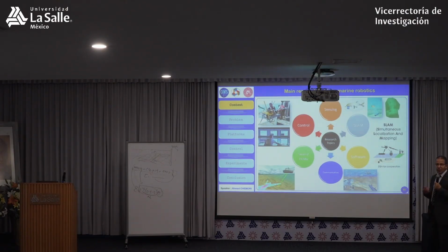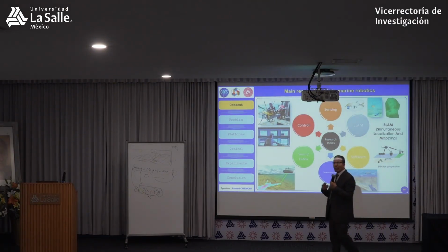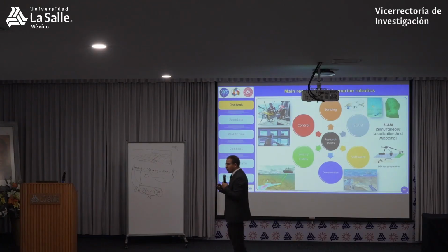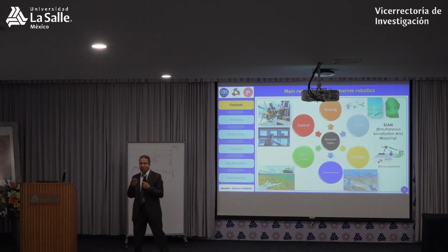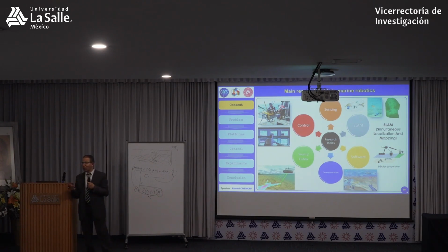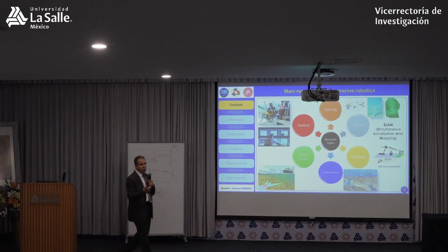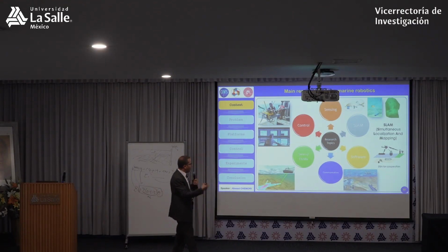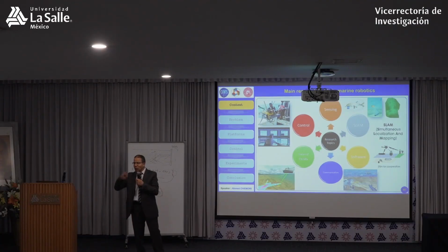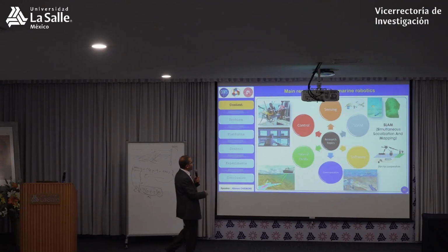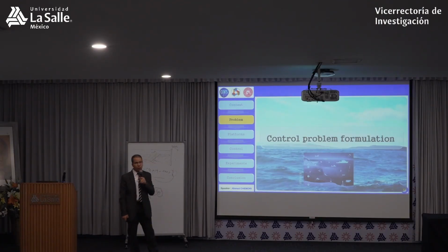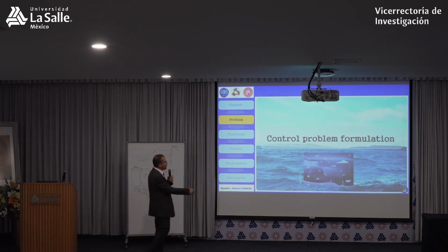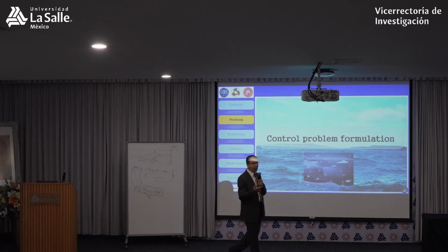And the last topic is the topic that I'm interested in. Whatever your underwater vehicle is, you need to develop a controller, because classical control will not work. If you design a PID for most of the applications, due to the environment, due to the operating conditions, due to the complexity, the PID will not work very well. In this case, you need to develop more sophisticated controllers, and this is why we are interested in this topic. And now, starting from now, let's focus on the control problem formulation.